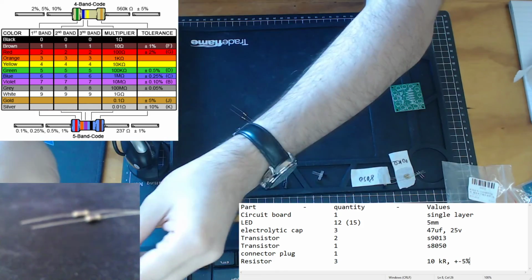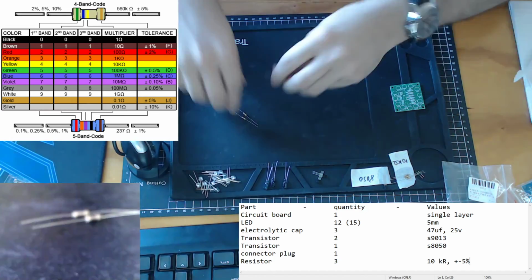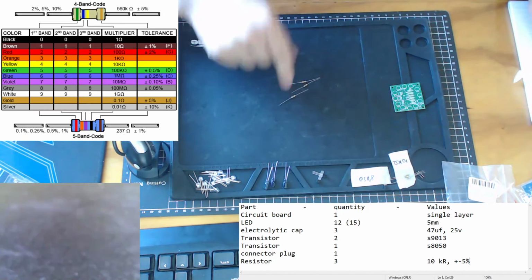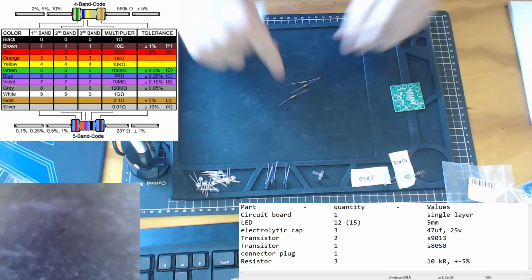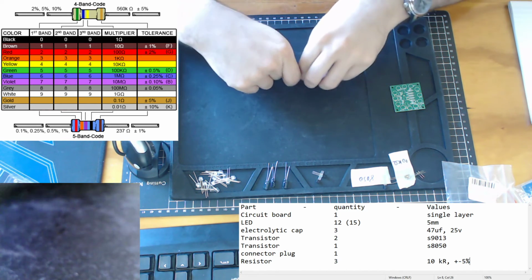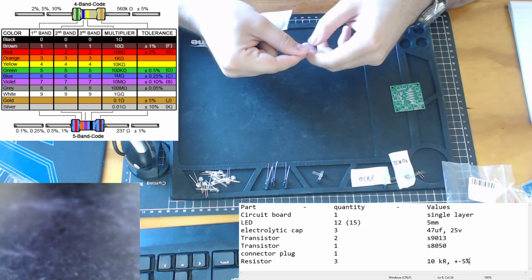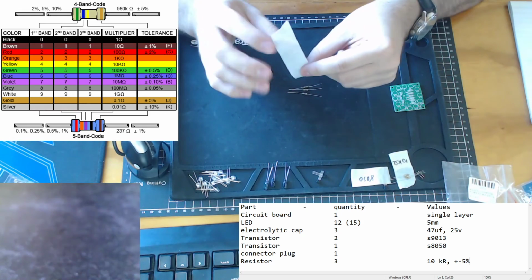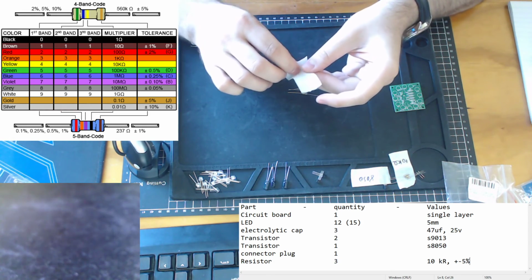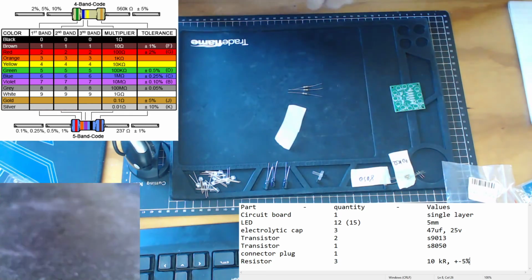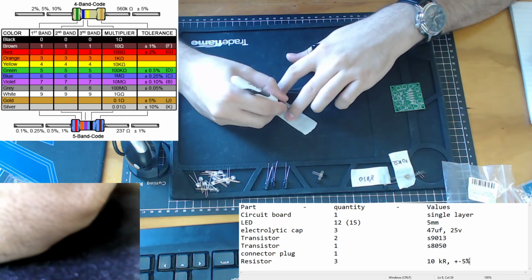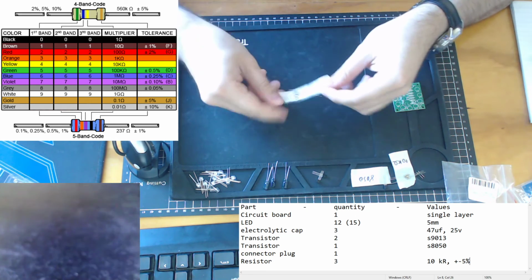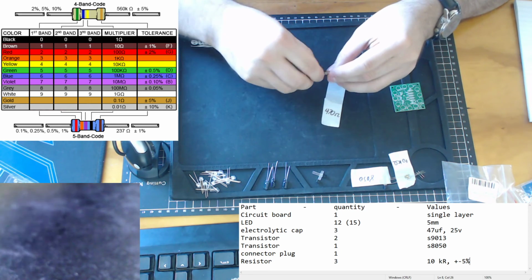Now we can use any sort of voltmeter that has a resistance checking capacity. It's a fairly standard feature, and something else we'd use in the workshop. Especially for these ones, if we have a large group of resistors, like if these fall into a bucket with other resistors, it's going to be very difficult for me to remember where they belong, especially if I don't know if they're in conjunction with this particular circuit, or if I'm giving this away when I'm building it. So again, I'm going to write down on my sheet here 470 ohms.